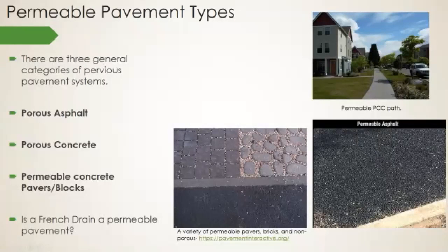And then we have more of an interlocking block system. They have little nubs around here that create these spaces or seams where we have that aggregate in between that again allows the water to percolate down, and there is very likely a couple of layers of different size aggregates of gravel to help with filtration, and then water holding as well, to help it move out into the soil layers. And those are the three main types.